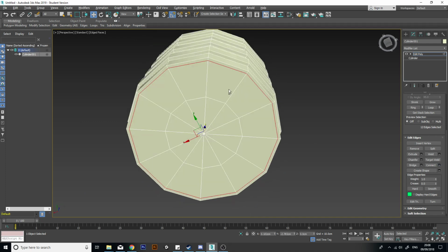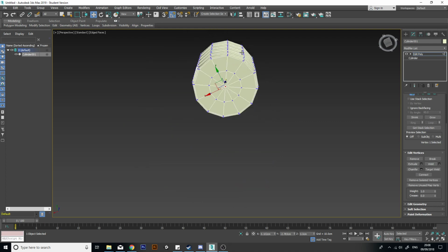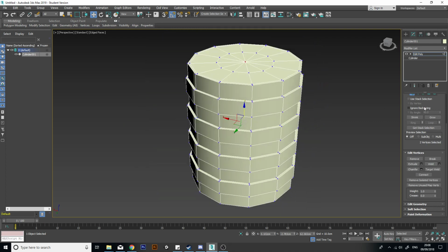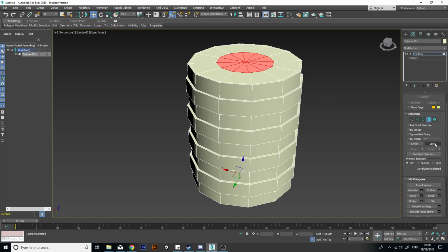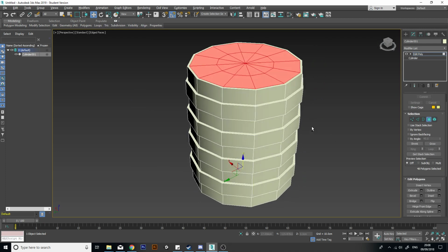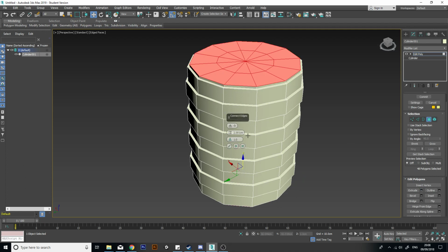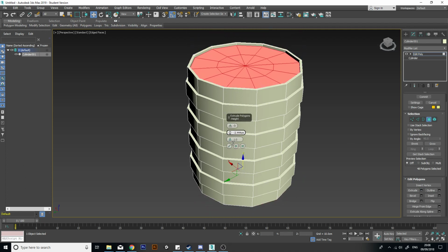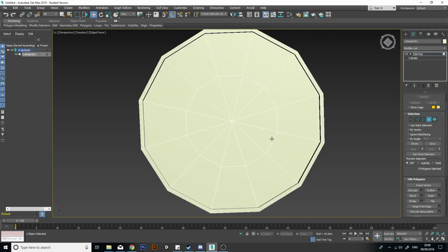And that'll be perfect. Now I'm just going to grab these two, change them to poly, and grow them, and then extrude negatively. Because if we extrude positively, they go out, extrude negatively, and now we have that beautiful lip. Just because I want to, I'm just going to make that 2.5. Perfect.